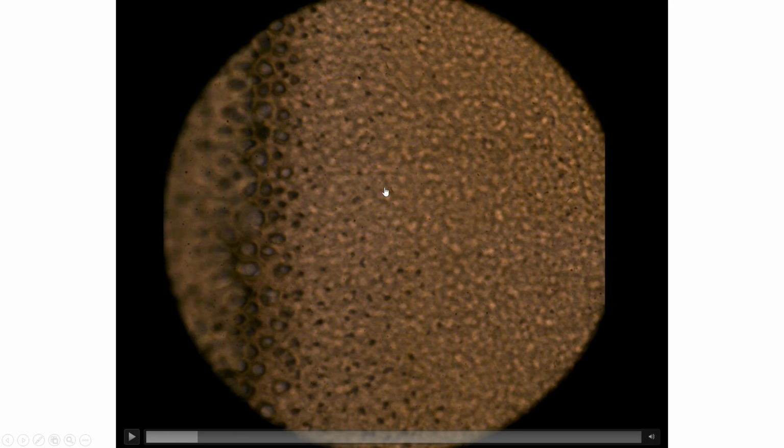We see that the adhesive remains bonded to almost all of the part over here, and now this is getting separated from this part. When it gets separated, the separation does not happen along a continuous line, but within a zone, by the formation of this kind of cavities. These are the kind of things that happen when we try to peel it.